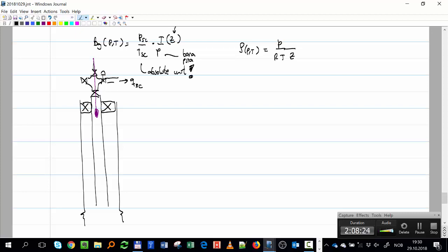And we have measured for different TVDs. So you get a table with TVD1, TVD2, TVD3. Or actually, it should be better if it's MD, with pressure and temperature. They are afraid that this well might be having erosion, that the velocity is so high that it's starting to take material out of the walls, and it can create all kinds of issues.